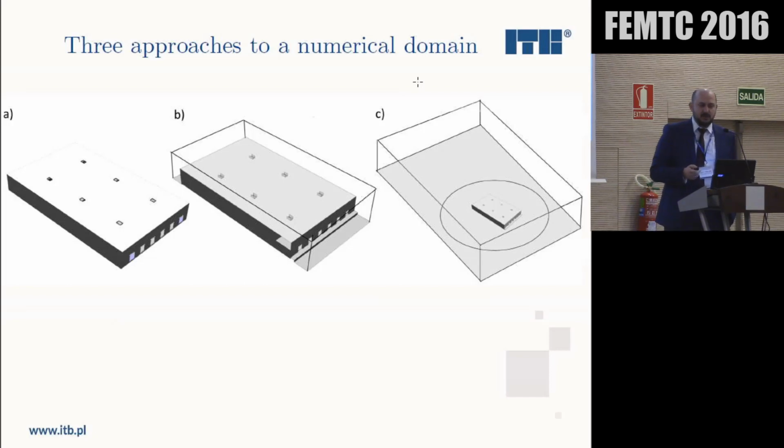First, the numerical domain and how you could build it with wind in mind. I've made 3 examples. One in which you would build just, let's say this room is our model. In this case, you would model just the room and openings like pressure inlets. So windows would be pressure inlets, and then you can apply a positive gauge pressure on these openings to simulate that positive pressure effect of wind. That would be one approach, and a lot of years ago, I have done that.